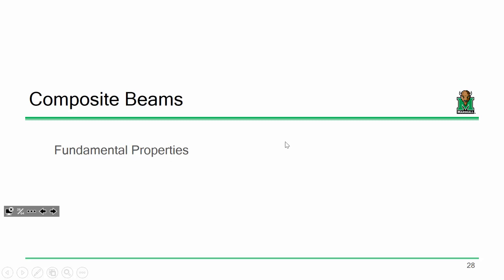In other words, I've been throwing some terms out at you over the past little lecture. Like I threw out what is MP versus what is MY, and I think later on last time we started to talk about D sub C, the depth of the web in compression and things like that. I'm trying to go back and explain a lot of this stuff before we dive into the spec. If we just started diving into the specification right now, specifically section 610, looking at the resistance, I'd have to backtrack so many times that we'd sort of lose touch with what we were talking about. So I need to go back and explain some of these fundamental concepts.